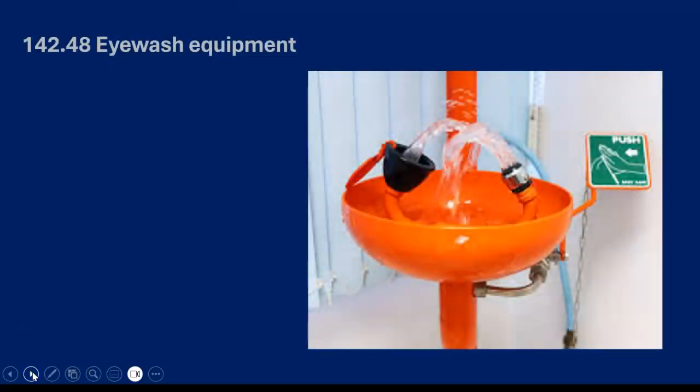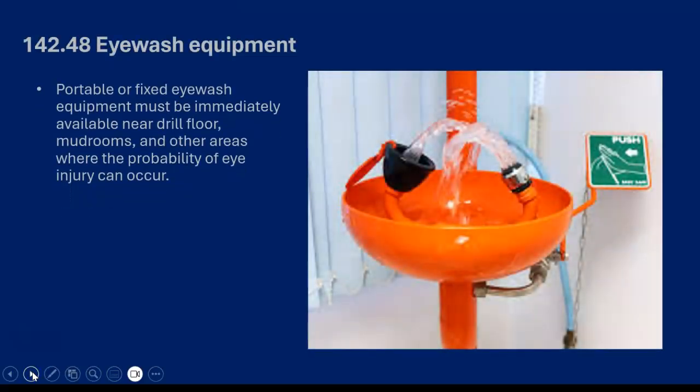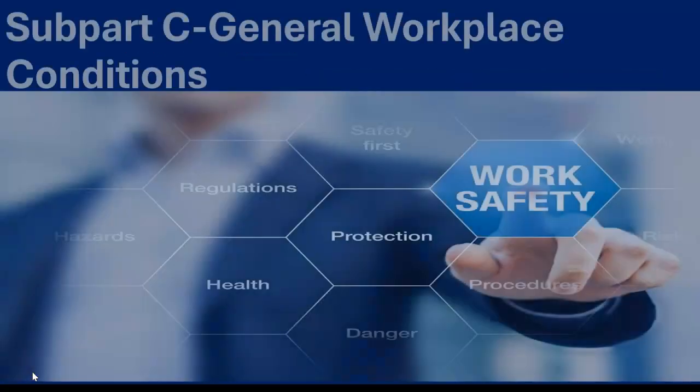Eye wash equipment. Portable or fixed eye wash equipment must be immediately available near the drill floor, mud rooms, and other areas where the probability of eye injury can occur, such as chemical areas.